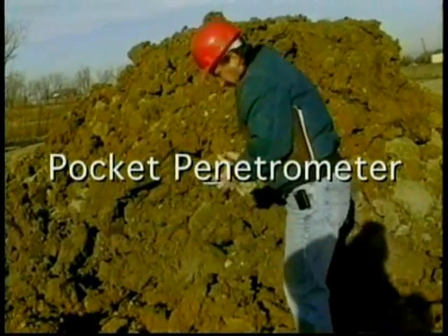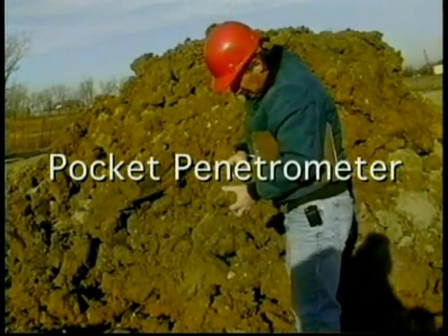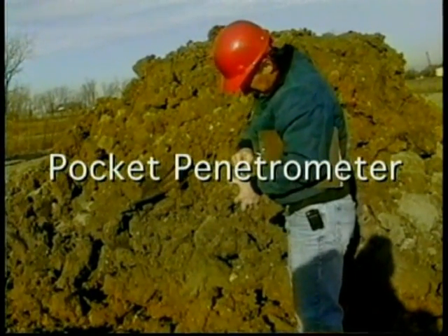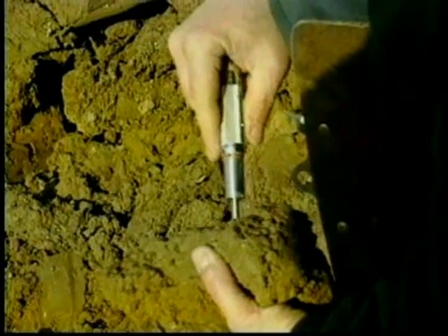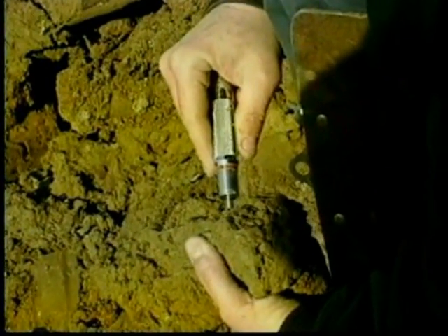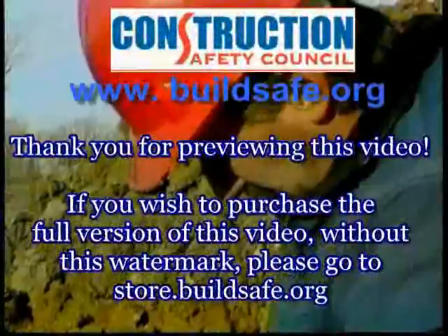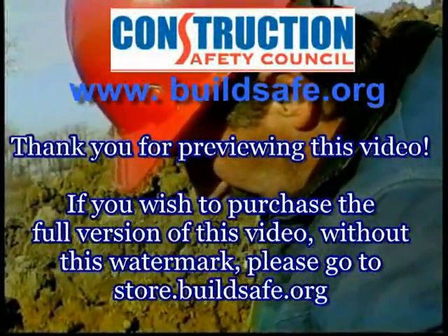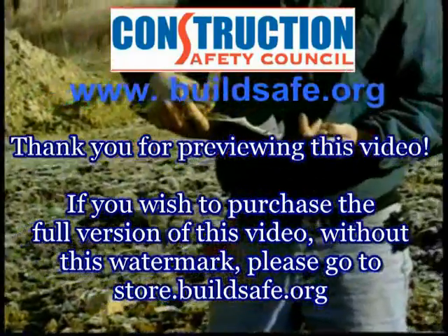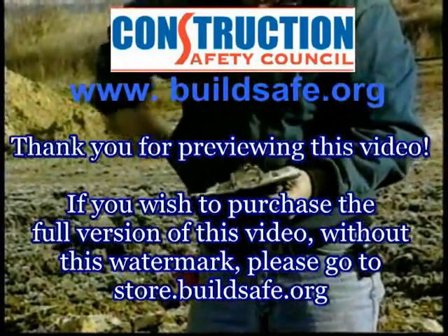The pocket penetrometer test directly reads the unconfined compressive strength of a soil. The penetrometer is pushed into the soil sample to the red line, then pulled out and read. The reading in tons per square foot will indicate whether the soil sample is type A, B, or C.